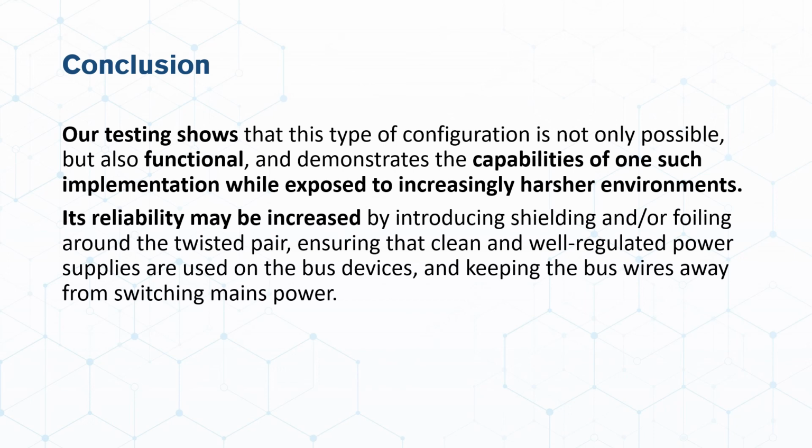Its reliability might be increased by introducing shielding and foiling around the twisted pair, ensuring that clean and well-regulated power supplies are used on the bus devices, and keeping the bus wires away from the switching mains power.